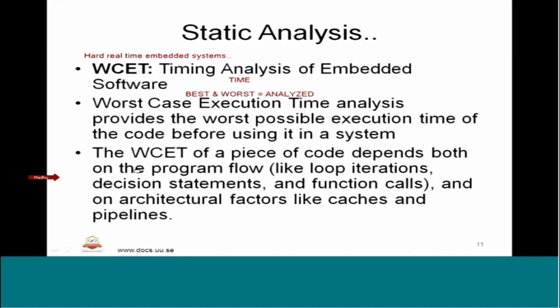The WCET, or worst case execution time analysis, of a piece of code depends on the program flow, like for loops and iterations, then decisions such as if else statements, then the various function calls within the program, and of course architectural factors like cache and pipelines.